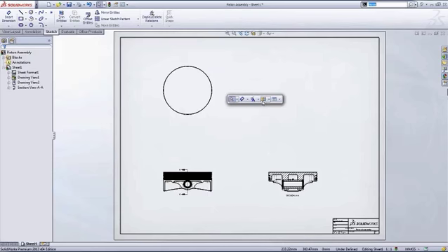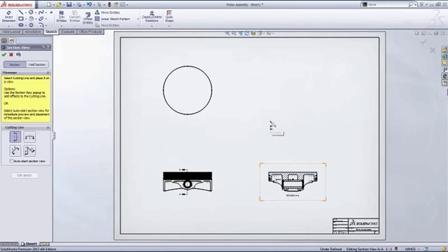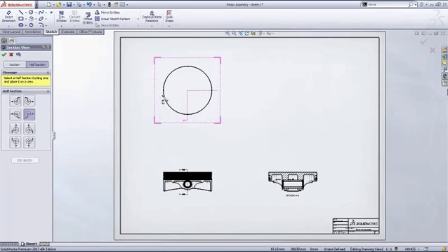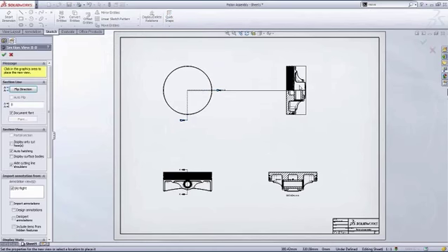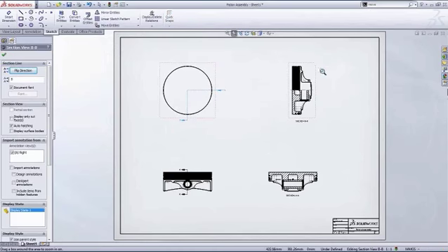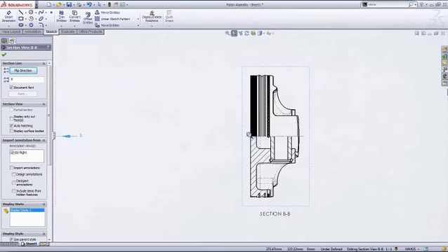Now, I want to look at one of my favorite things we can do with views in SOLIDWORKS. I'm going to create a half section through the top view, and though this makes a nice view by itself, I want to show something really cool. To get a better understanding of this view, it might be convenient to look at this in an isometric section